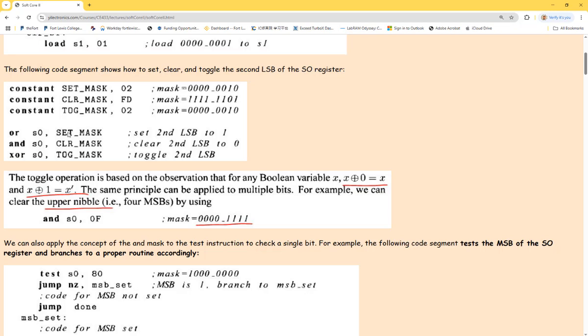Okay? And the second one, clear bit 1. Now it's changing the register. It clears bit 1 of S1 and sends the result to S0. How to clear it? Do an AND operation, with that certain bit being 0 in the mask, but all the rest should be 1s.